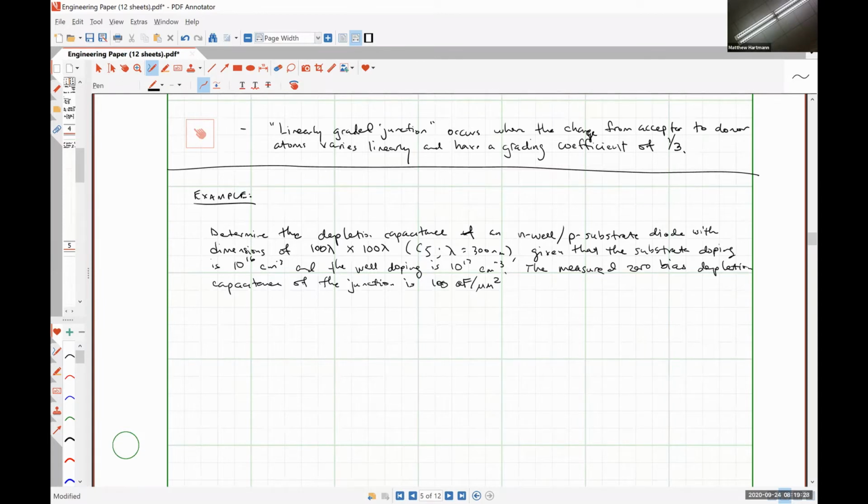And so it's not going to be uncommon for us to see units of actual capacitance per square micron for some things, particularly what we will call area capacitances. And then we're also going to have fringe capacitances, which we'll talk about a little bit later, where we're going to see that those are measured in farads per micron, so not squared. And it's because the thickness value for the fringe capacitance is usually fixed, so it's built into the unit. Anyway, let's get back here.